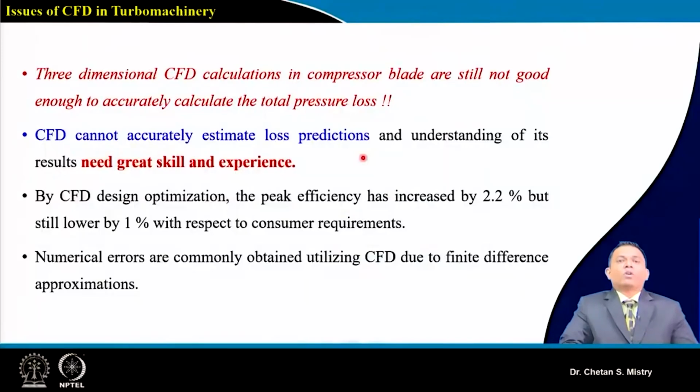So overall, if we discuss, there are certain issues with CFD analysis. Three-dimensional flow, what we are looking at for the compressor, still as of today, the results are of question mark. These codes are unable to predict the total pressure loss. At the same time, to have an accurate prediction of the performance, a whole lot of skill and experience is required.